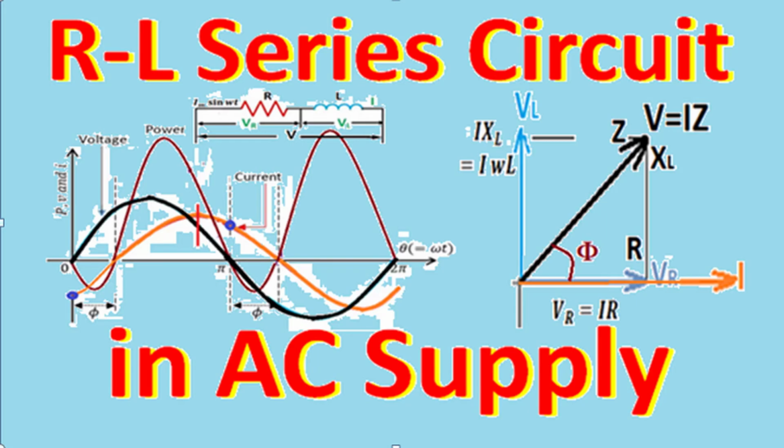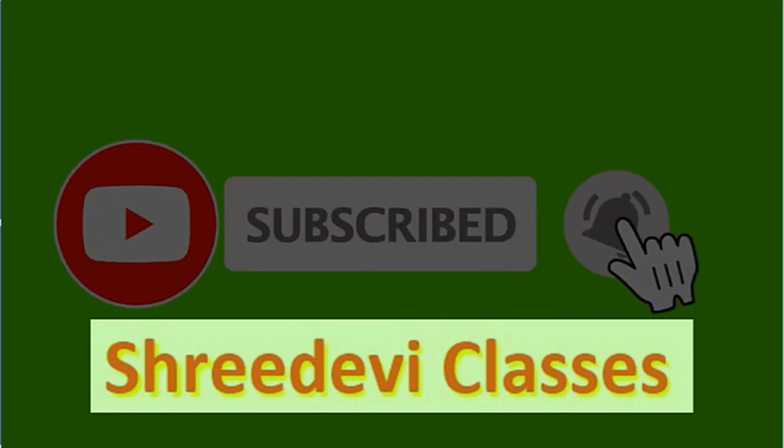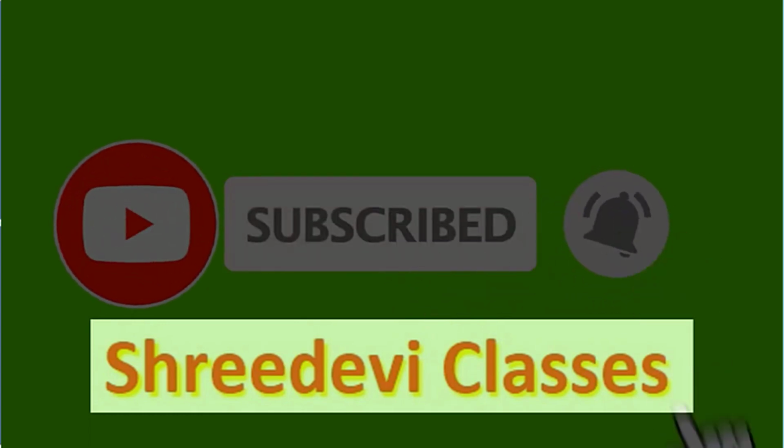This beautiful small learning video has explained behavior of resistance inductor series circuit in sinusoidal alternating voltage supply, and now you understand the concept of impedance and impedance triangle, and the same impedance triangle becomes voltage phasor diagram, and angle between impedance and resistance becomes angle between supply voltage and circuit current, and since impedance is clockwise to resistance, XL is plus j type, voltage leads current or current lags voltage.